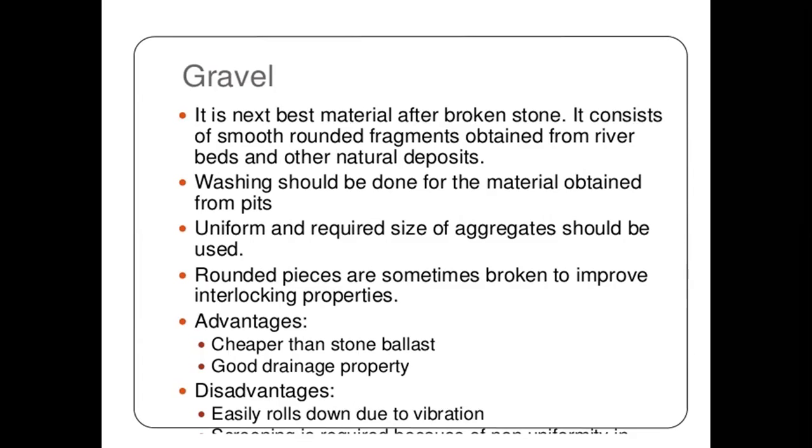The major advantages are that it is cheaper than stone ballast and has good drainage property. The major disadvantage is that it easily rolls down due to vibration.